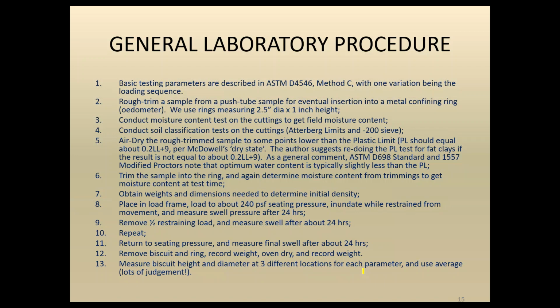And by the way, that can involve a lot of judgment. The measurement here of the dried biscuit is not a rigorous parameter. It's more of an indicator. For example, if a sample that had a very high PI was tested in a pressure swell test and you didn't get much swell at all or much pressure, and that's of course completely unexpected, then it's very likely that that sample was put in a fairly wet or pre-swelled condition.